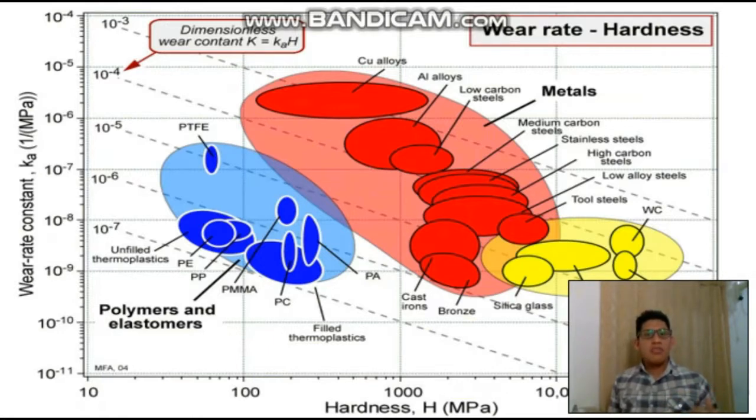The wear rate is measured as volume in cubic meters over the force in Newtons times distance in meters, which results in 1 over megapascals. It should be mentioned that the wear rate is not strictly constant, but remains constant after a period of transition. For the same purpose, material development is necessary to have some universal quantitative parameter for wear. In many cases, it's most relevant to compare the wear properties rather than only the friction properties.